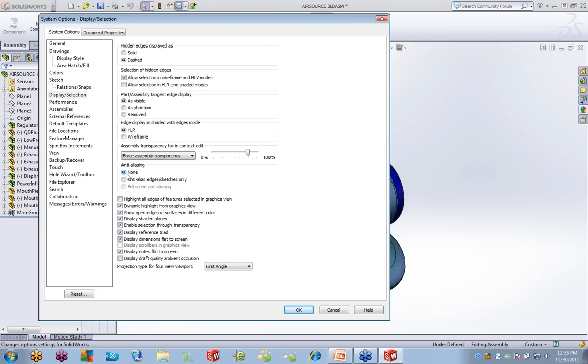Have they added a system option for configurations for this configuration change only? And the answer is no. They have not added that as far as the default. It's been asked quite a bit. For those who are wondering what that means, when you go to make a change with parts with configurations, you have the choice between this configuration, all configurations, or specify. What's being asked is if I can set a default so that I know it always goes and changes all, or changes this, or a specified set.